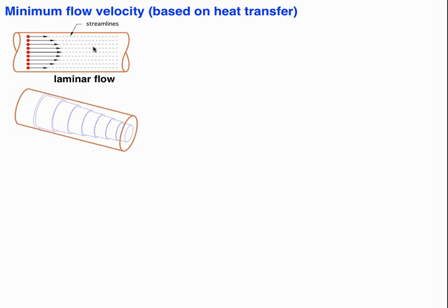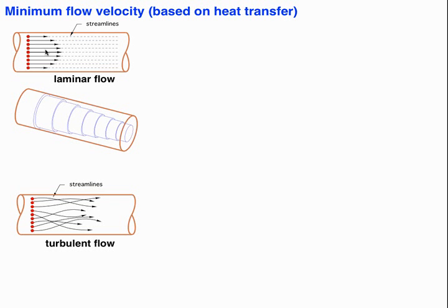And you can almost think of this as sort of telescopic cylinders, the way this shows down here. Again, the molecules near the center of the pipe are moving faster than the molecules that are closer to the edge of the pipe or the inner wall of the pipe, but they aren't mixing. They're all flowing in these parallel paths. It's sort of like many, many lanes on a highway where none of the cars are changing lanes. Everything's staying in the same lane.